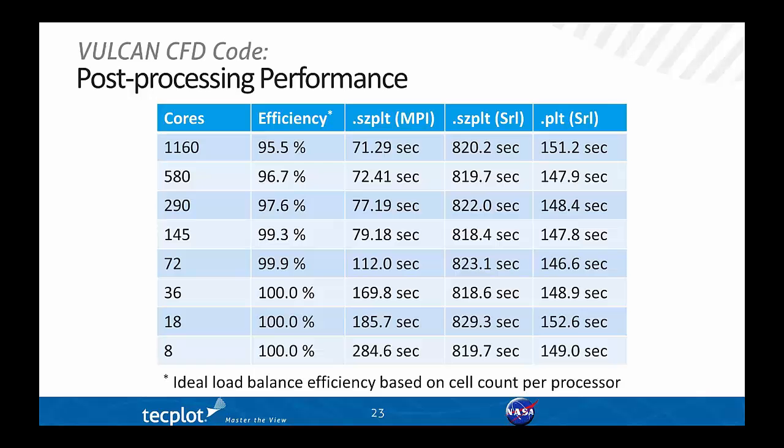So good. And you mentioned to me that you had gotten an idea of what it took to do the Plot3D output for this case. Yeah, that took about 3 minutes, a little bit slower than the serial .plt format. That's because, as I said, on that post-processing pipeline the first 2 steps are in parallel, so they were pretty quick. But the last step was serial, so that's the bottleneck. It basically scaled pretty well with the serial .plt column here, but a little bit slower.